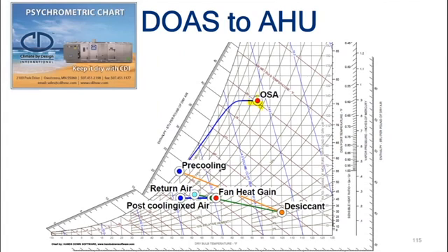This is what it looks like on a psychrometric chart. We're going to take the 4 air changes of outside air. I'm showing a pre-cooling coil. Now we can get by with just your normal 45-degree chill water or 45-degree DX system, whatever pre-cooling we'd want to do. It can even be heat recovery, although that is becoming less and less of an option in hospital operating rooms or anything like that. So most of the time it's going to be some sort of coil.